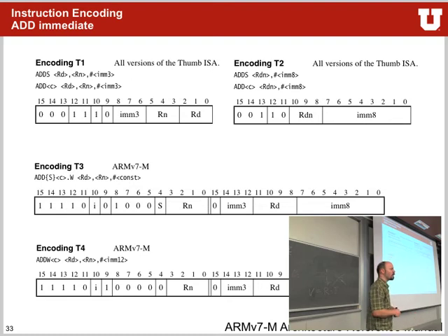So what do we do if we want to access another one, one of the higher ones? You have to use a different encoding. Exactly, right? So the key here is the ARM ISA is actually dynamic. Sometimes you can have 16 bits for an encoding, sometimes 32 bits. Of course, if you use only 16 bits, you can have 2 instructions in one 32-bit word. That makes the whole thing a lot faster because you have one memory access, read 32 bits out, and have 2 instructions that you can start executing immediately, instead of going one by one by one. It speeds things up, uses less memory space, etc.